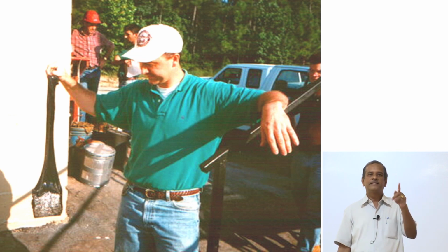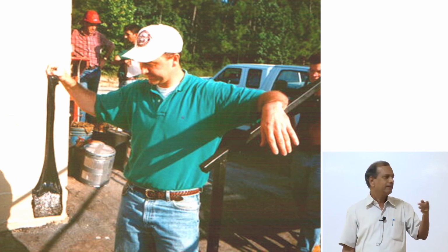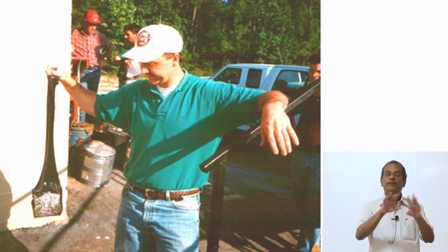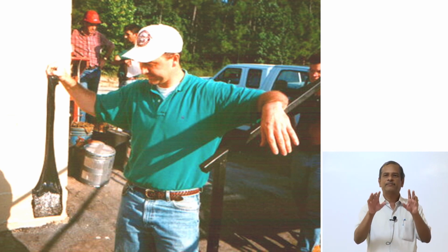So again, the challenge before you is what type of modification is needed for the bitumen, what will be the increased cost, what will be the performance of this high performance bitumen. As you know, the cost of bitumen will be around 30,000 rupees to 35,000 rupees per metric ton. When I try to modify the binder, the cost will go up to 40,000 to 45,000 to 50,000 rupees. So should I spend more money? Yes, it can perform better. But again, you have to find out there are different types of modified binders. Which one to select is again based on the recommendation of the civil engineer.